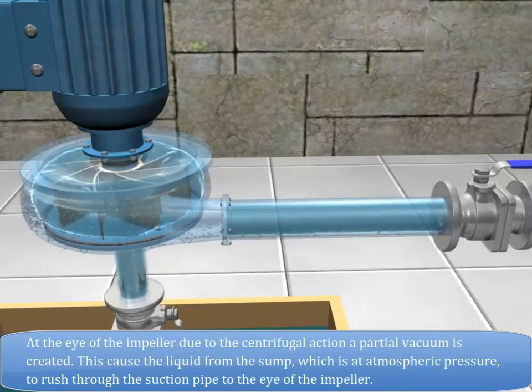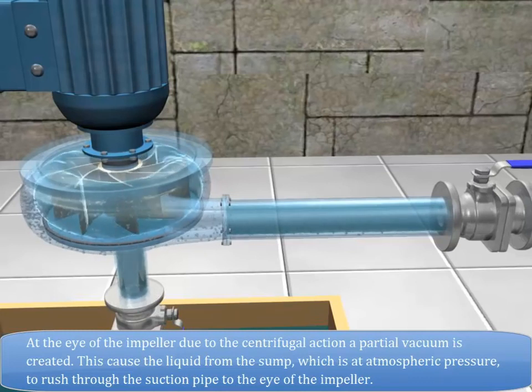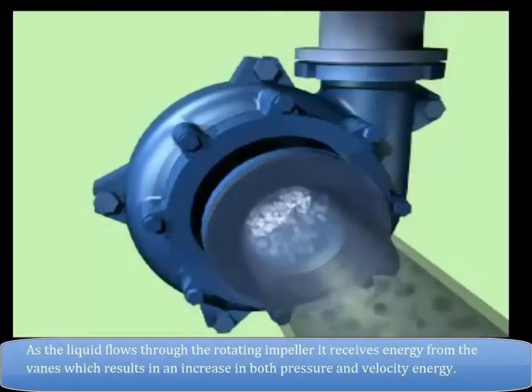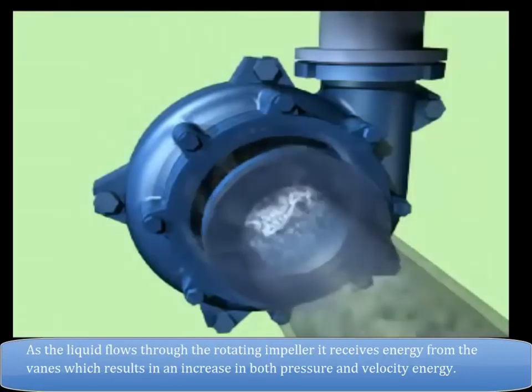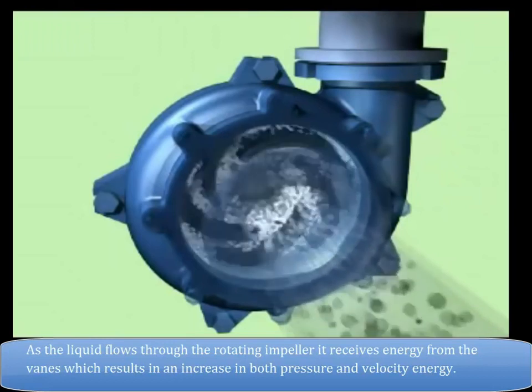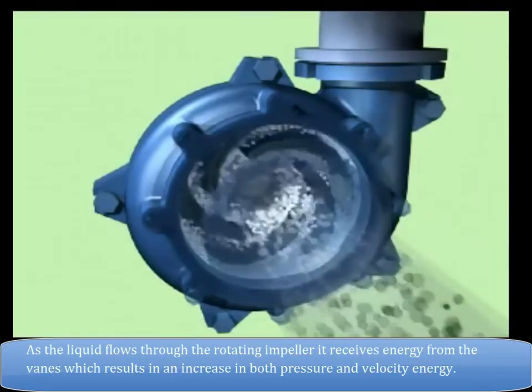This causes the liquid from the sump, which is at atmospheric pressure, to rush through the suction pipe to the eye of the impeller. As the liquid flows through the rotating impeller, it receives energy from the vanes, which results in an increase in both pressure and velocity energy.